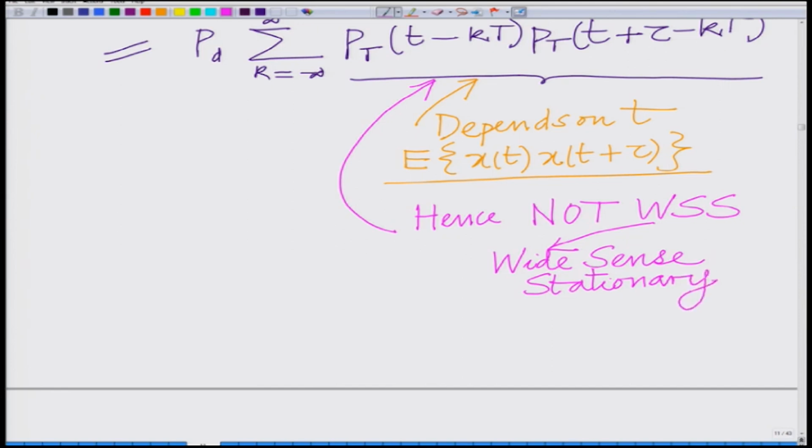We would like to therefore convert this, because remember, wide sense stationary signals are very helpful to us because they are suitable to be studied, easy to analyze and characterize, and more importantly we can evaluate their power spectral density to characterize the spectral distribution of the power. So, we want to convert this digital communication signal, which is not wide sense stationary, into a wide sense stationary signal.